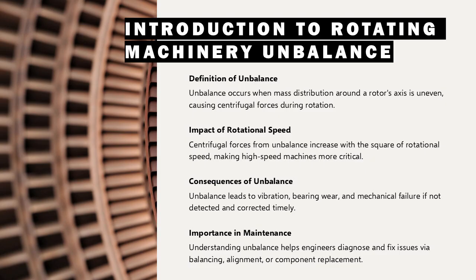Unbalance in rotating machinery refers to a condition where the mass distribution of a rotating component is not symmetrical about its axis of rotation. When such a rotor operates, centrifugal forces are generated due to this uneven mass distribution. These forces act radially outward and increase proportionally with the square of the rotational speed, which makes unbalance especially critical in high-speed machinery. Even a small mass deviation can generate significant dynamic forces that are transmitted to bearings, shafts, and supporting structures. Over time, these forces lead to elevated vibration levels, accelerated wear, and eventual mechanical failure.